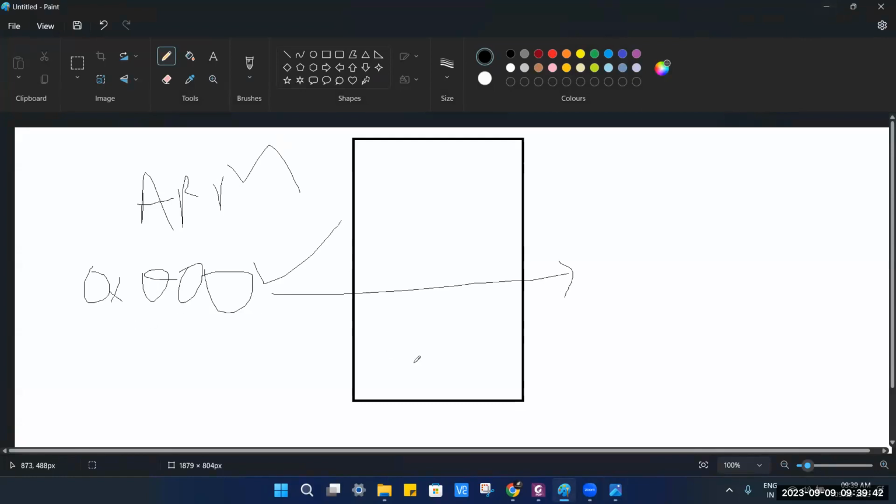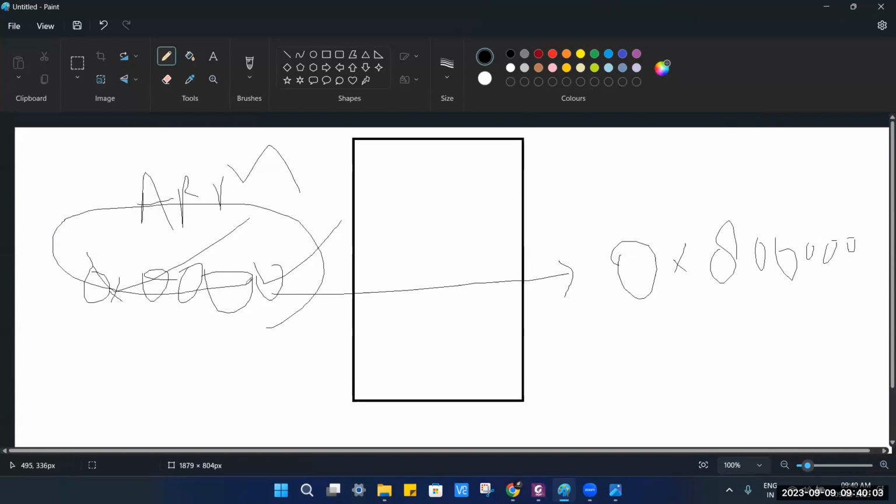Yeah. So let us suppose it tries to read from 0x0000 something. It will fetch the same value from 0x08000000, where I have put my bootloader. Yes. Correct. So once power on reset happens, the value stored at this address gets saved in the stack pointer, which you can say is the main stack pointer, MSP. Yes. Okay. Then after that, it will start fetching the data from 0x0004.